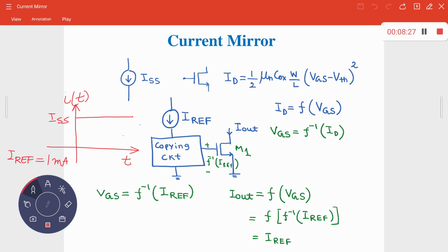Okay. So first of all, whenever we go for the design of the current source, obviously we have to ensure that the transistor, this MOS, must be operating in the saturation region. That is quite obvious. It must not operate in the triode or deep triode, because if the MOS is in the saturation region, then only you can expect that this current ID, if I neglect the channel length modulation, is equal to half mu n C ox W over L into (VGS minus VT) whole square. If I design this current source using an NMOS device it's mu n, otherwise it will be mu p.